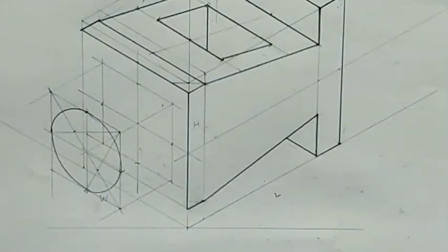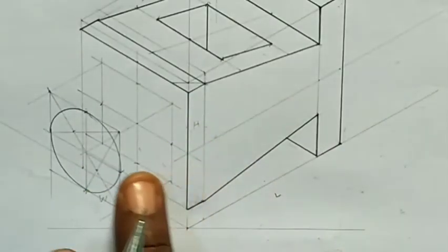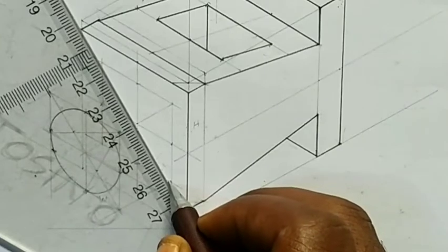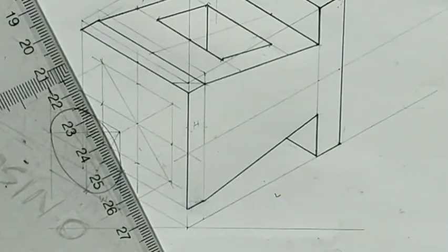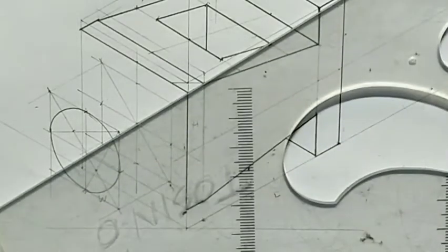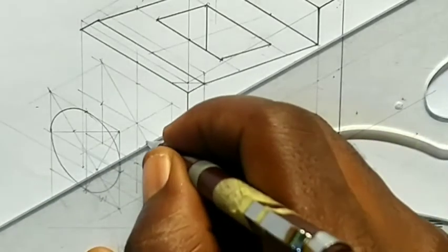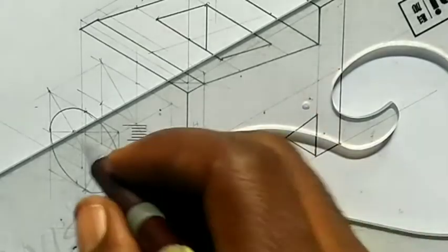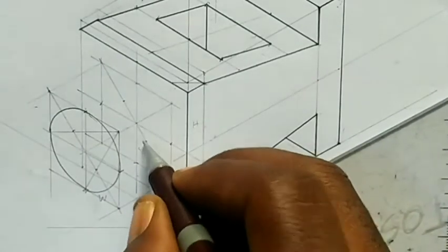So after I've done that, what I'll do is I'll replicate what I did here inside too. If you see, I have another box inside. So I'm going to join this aspect to this aspect here. So instead of me wasting my time I'll just transfer my point. So place my set square on my t-square. Now move this center point I used to draw my arc. I'll move it to this point. I'll come here to do the same thing from this point to this point. I'll move it to the diagonal here. So I've done that.